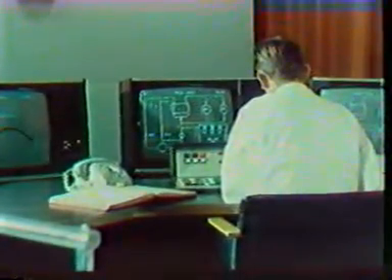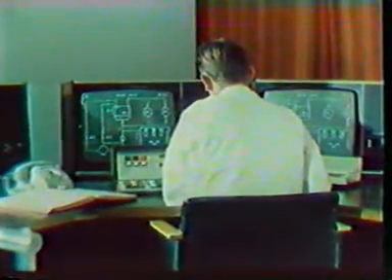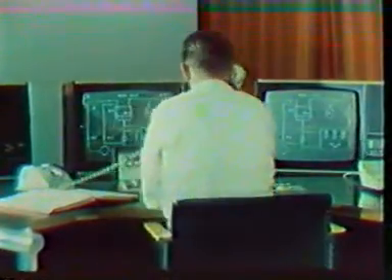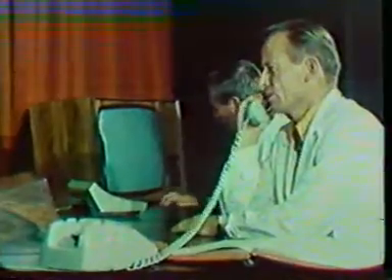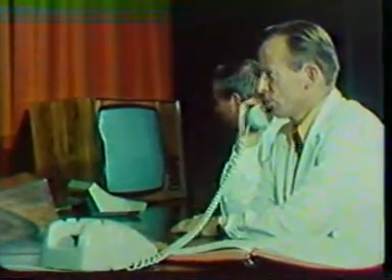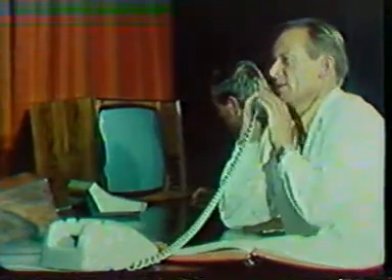For the operation of the Halden reactor, a number of supervision and control functions were implemented, which the reactor operator can control from the console. Both he and the plant supervisor can call up plant variables and their limits, change the limits, activate control loops, operate pumps, valves, and control rods, request trend curves, mimic diagrams, and so forth.